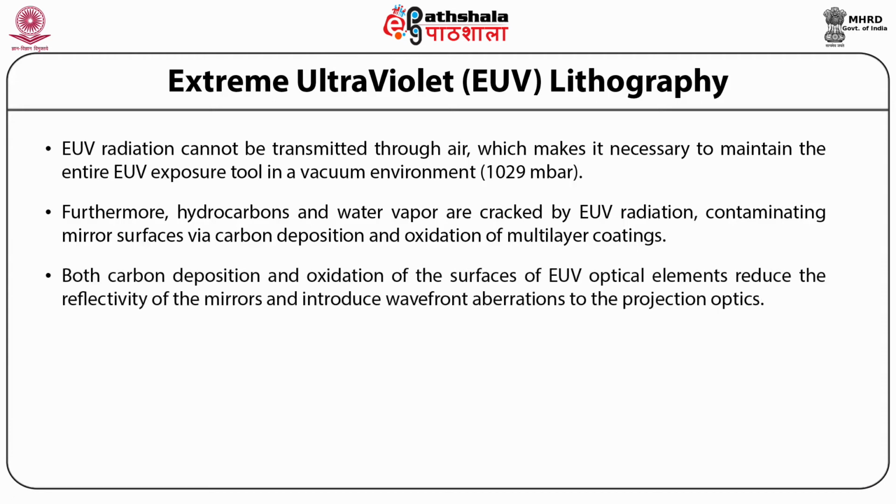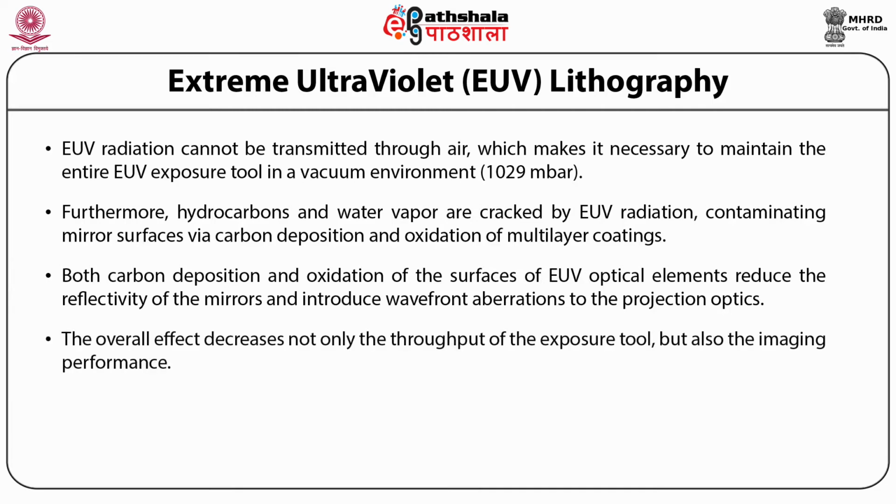Both carbon deposition and oxidation of the surfaces of EUV optical elements reduce the reflectivity of the mirrors and introduce wavefront aberrations to the projection optics. The overall effect decreases not only throughput of the exposure tool but also the imaging performance.